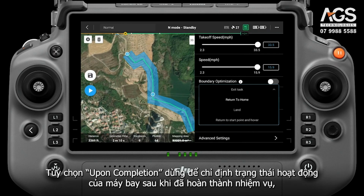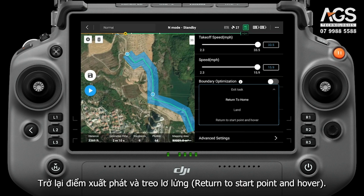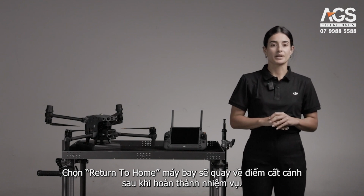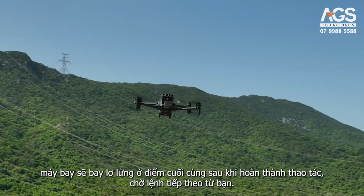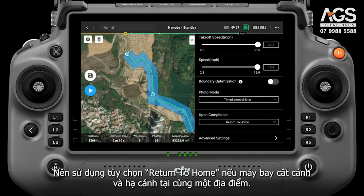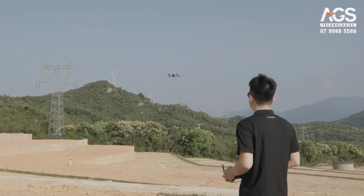Upon completion is the flight action when the aircraft has completed the mission. It includes 4 options: exit task, return to home, land, return to start point, and hover. The default option is return to home. Select return to home, and the aircraft will return to the home point after completing the mission. If you choose to exit task, the aircraft will hover at the last waypoint after completing the operation, waiting for your next command. Return to home is recommended when takeoff and landing are at the same location. You can choose exit task mode if you follow the aircraft.